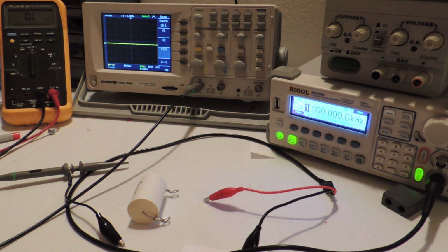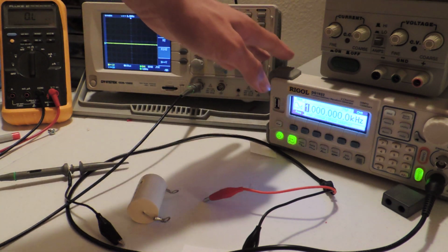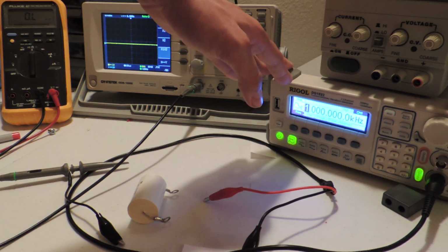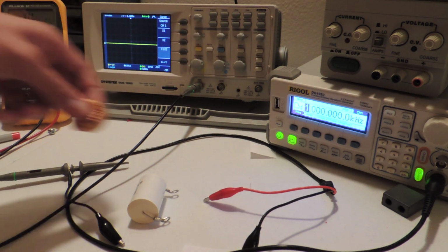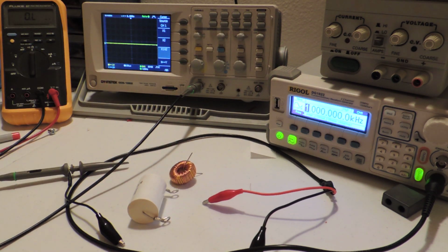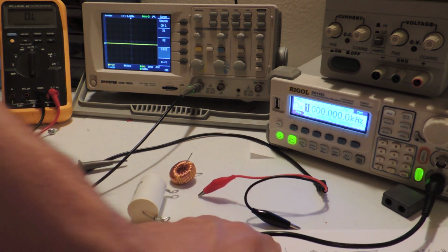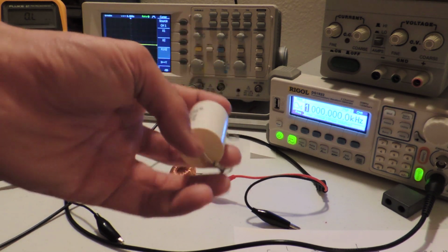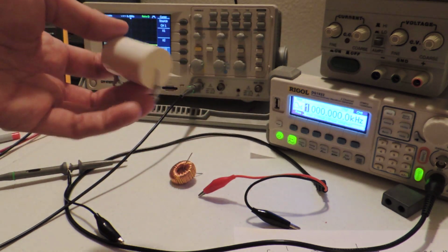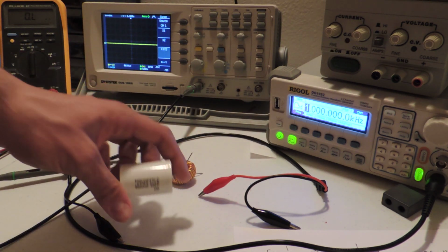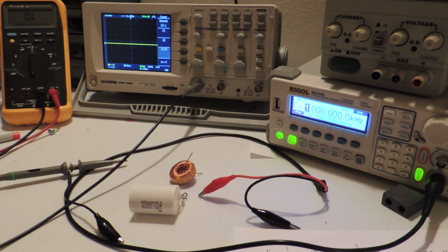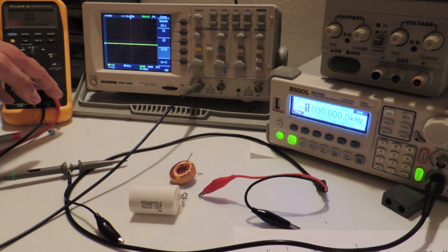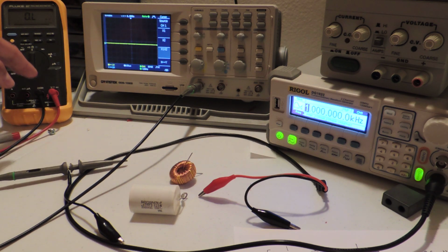So for starters, let's talk a little bit about what we actually need to do this. As I stated before, you're going to need your scope and your signal generator, or some method of creating a variable frequency signal at a constant amplitude. You will need a capacitor of known value. It cannot be electrolytic. It has to be polypropylene or ceramic disc or some other type of non-polarized capacitor. And optionally, you should have a multimeter that can measure capacitance. This is a pretty common feature on most multimeters, and most of you should not have trouble with this.